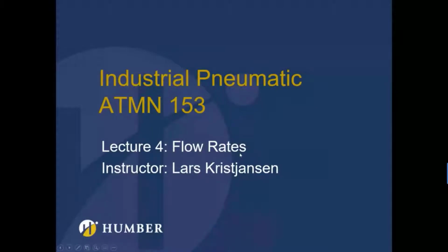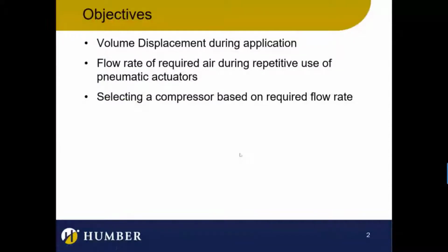Welcome to flow rates. Okay, here we go. So what we're going to be discussing is the displacement of volume during application, during the extension and retraction. So I talked about that. I showed you practically with that cylinder. And the flow rates are required because what's happening is that those actuators repeat their actions all the time.